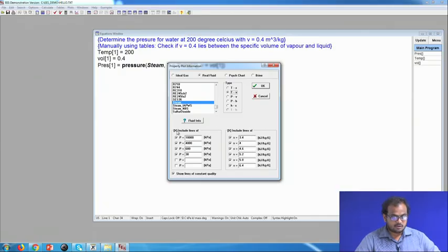Then additional things that you have include lines of. Okay. So, let us deselect these for now. So, these are isoentropic lines, these are isobars. In our particular case, let us draw two particular isobars, one at 500 kilopascal and one at 400 kilopascal, because we already know that the solution is 540 point something.